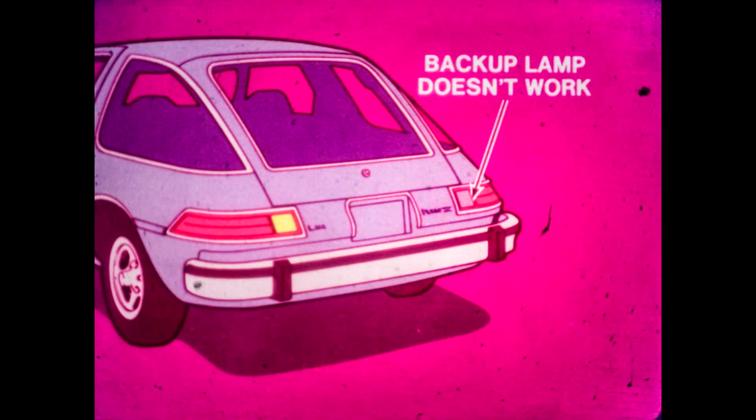Let's go to our backup lamp problem again, but this time, let's say only one backup lamp doesn't work. It's time for some forward diagnosis. We could use common point testing to track down the problem, but even better, take a moment to think through the problem. It's pretty obvious that the backup switch is working. Otherwise, neither backup lamp would work.